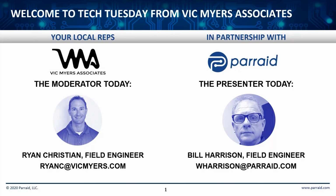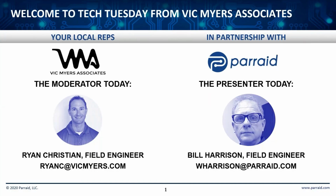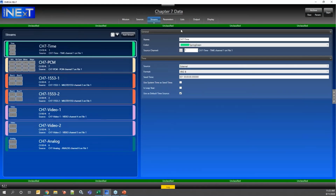And it looks like the first one that I have here for you, Bill, could you elaborate what if the data source is TM over IP? Sure. TM over IP just means that instead of coming through the air as PCM, it probably is coming through the air as PCM, but when it hits the receiver, it's being converted to telemetry over IP.